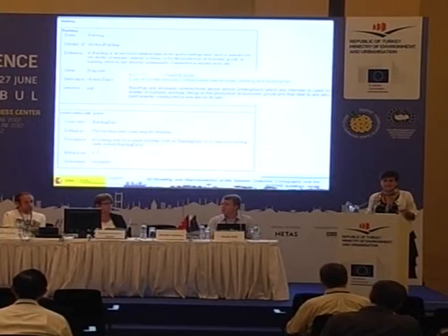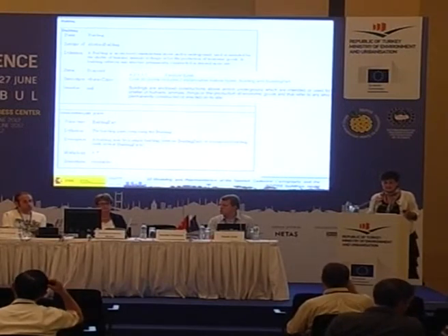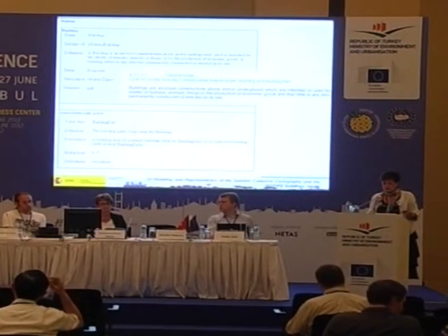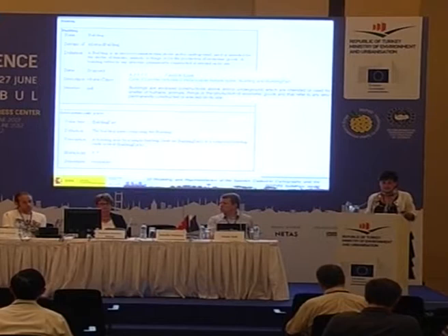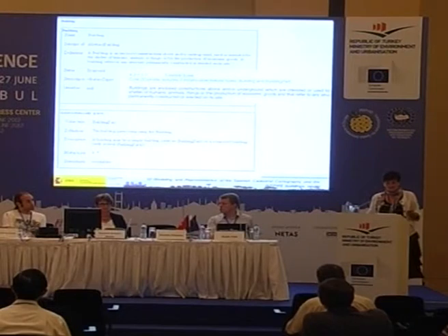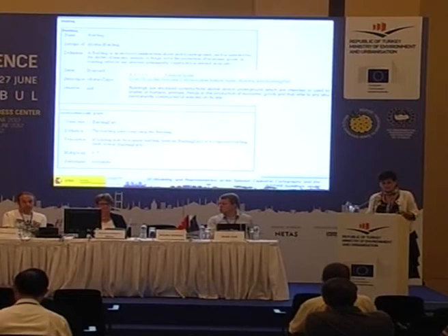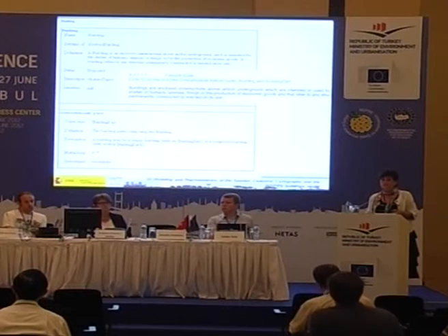What the INSPIRE specification says is that buildings are enclosed constructions above and/or underground, which are intended or used for the shelter of humans, animals, things, or the production of economic goods, and that refers to any structure permanently constructed or erected on its site. But then it says that the building can have building parts, and the building parts compose the building. A building may be a simple building with no building parts, or a composed building with several building parts.